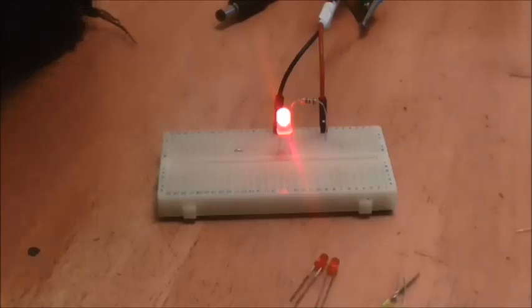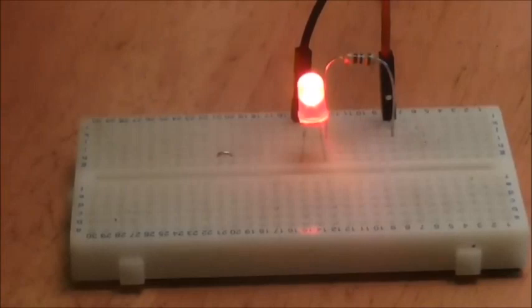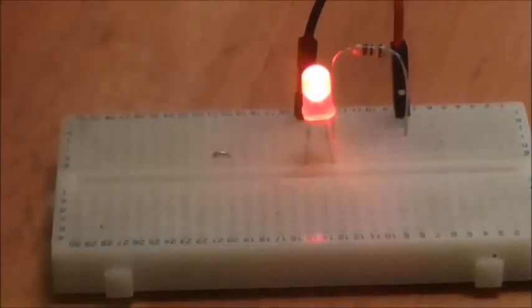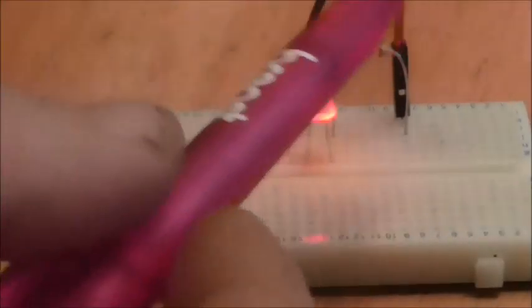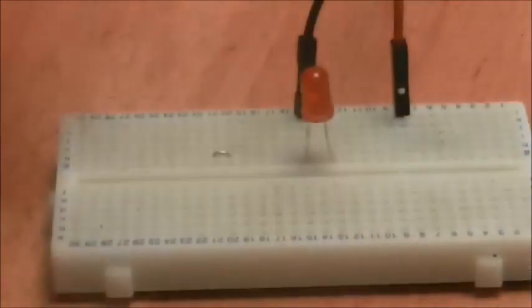So, as I promised, we'll have a look at the forward resistor, and then we'll get on to a little bit more theory, and we'll look at a practical circuit. Now I use a 540 ohm resistor here, and you can see that the LED shines quite brightly, quite nicely. But I'm going to take the 540 ohm resistor out, and I'm going to put in a resistor that is a bit too small, and let's see what the difference is.